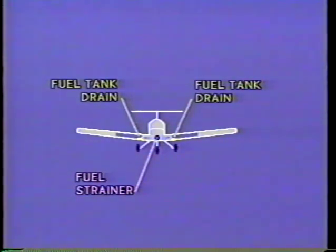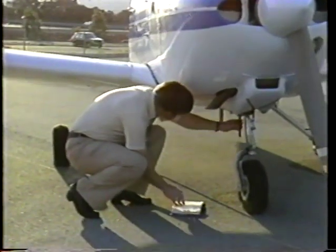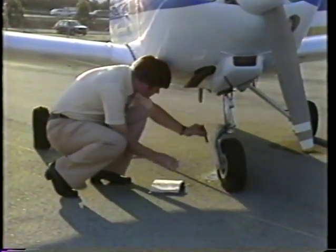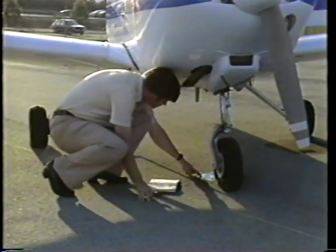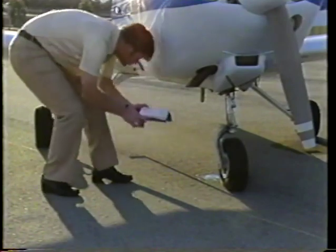This is the low point in the system, and the aircraft will have a drain on this point. During the pre-flight you can drain the fuel from there, and if any water condenses in the system, it can be drained out at this low point, since it will settle there as water is heavier than fuel. And from there it goes up to the engine-driven pump and on to the carburetor.